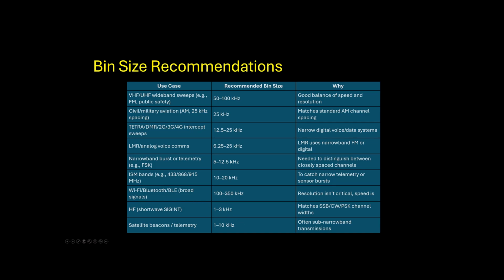You might want to go even higher if you're looking for Wi-Fi, Bluetooth, even though this really isn't in scope for the RTL-SDR because it only goes up to 1.7 gigahertz. Now, there's plenty of voice comms there, and there's plenty of data comms, but anything else, you're going to need to build something like this on your own or use another tool. Maybe not with a HackRF, because while it does support 20 megahertz, it's not exactly precise.